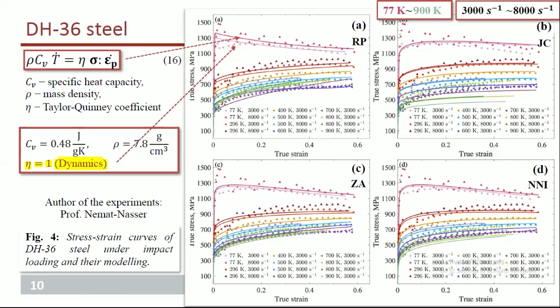As a result, the heat generated by the plastic deformation cannot escape from the material, but remains trapped inside, raising its temperature during the deformation process and therefore reducing the stress level. This is a typical stress relaxation process and a very special thermal softening behavior of materials under impact loads, although you can find hardening behavior in other loading conditions.